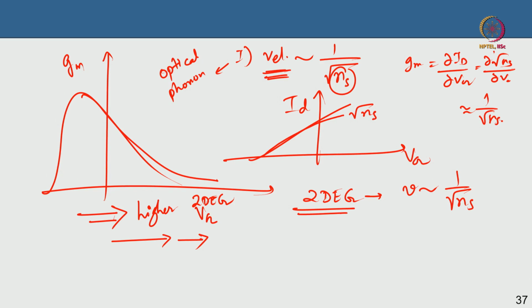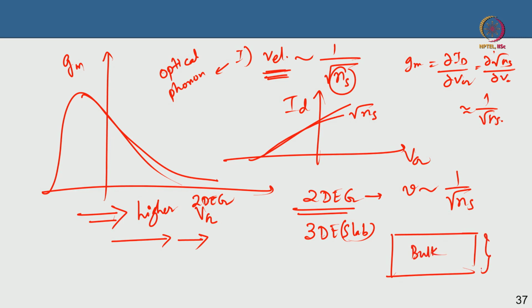We will not call them a gas, but we will call it a 3D electron slab. It is like a MOSFET, it is a bulk doping. If you take a layer of gallium nitride which is bulk, say some 30, 40, 50, 60 nanometer, which is n-type doped, it is like a MOSFET, then you are going to mitigate this issue. But a MOSFET is not good because your scattering will be too high because of the ionized impurities, right, background impurities, so your mobility will be low.